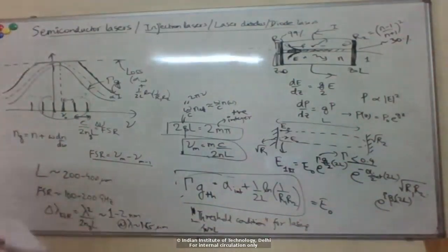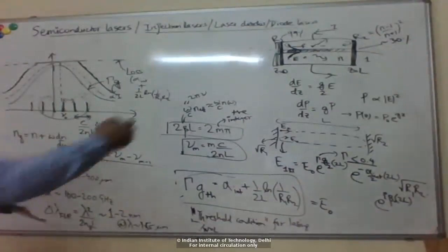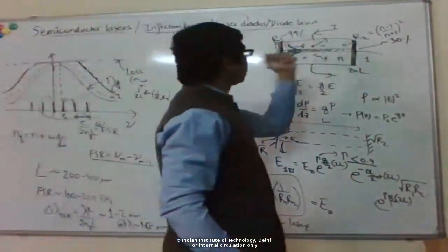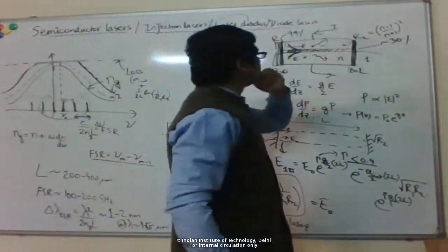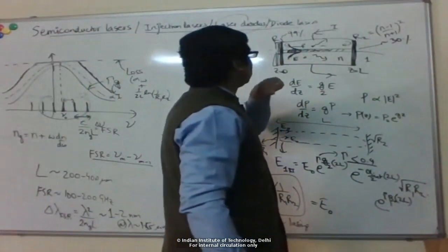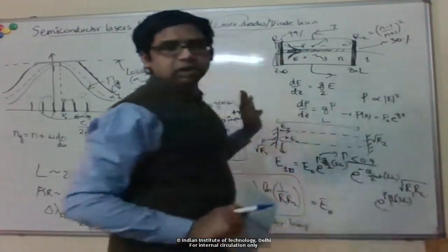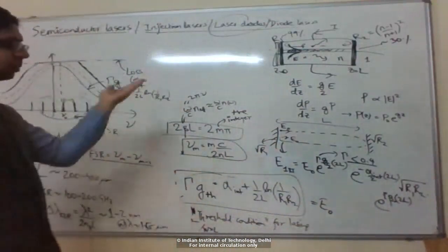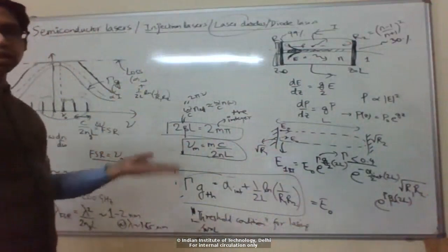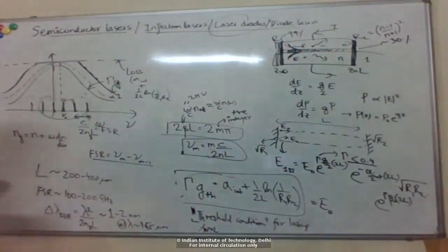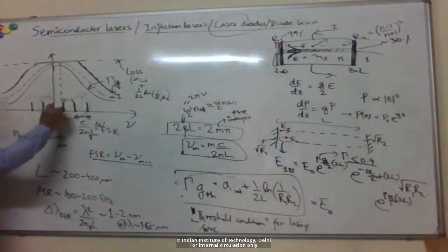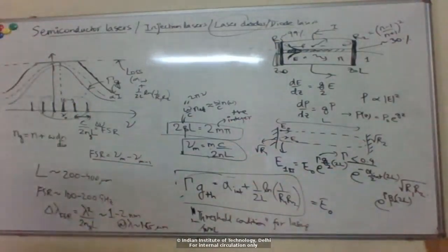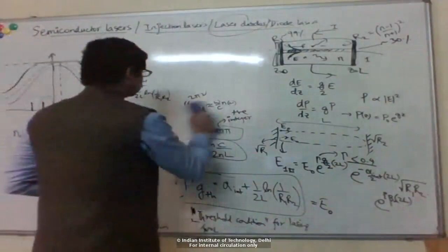Okay, so this is the regime where so-called laser diodes operate. Laser diodes are basically semiconductor PN junctions with an active region, cleaved facets, maybe one polished facet, and that's about it. With such a device, once you operate above threshold, let's say your current is about twice or thrice the threshold current, you have a situation like this, where multiple modes are lasing.